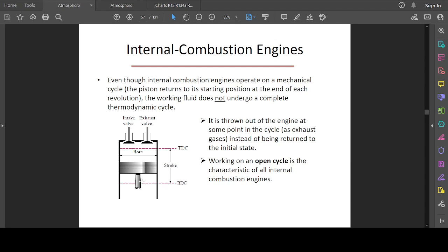The piston returns, and what we have here now is the remnant, the byproduct of combustion from that spark ignition explosion, and that combustion product will exit here. As the piston is returning, the exhaust valve opens to allow the byproduct of combustion to leave, and the piston will always terminate its stroke at the TDC, the top dead center. There is a reason for this: to minimize faults in the engine.